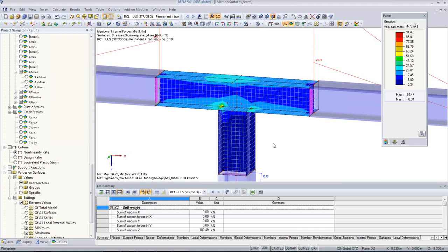The way the software works, it compares the existing stress with the limit stress, the yield stress of the material, and then has an algorithm in there that reduces the stiffness and the elasticity modulus of those elements. Because we can only reduce the stiffness of the entire finite element, we cannot evaluate, or we should not evaluate, the result separately in each node of the finite element.